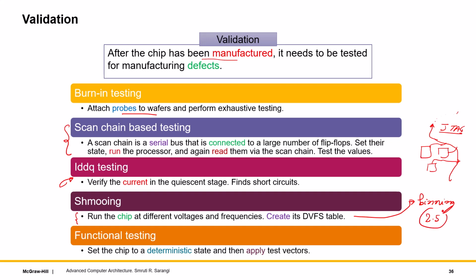So we'll sell a 2.5 gigahertz chip and of course charge less than a 3 gigahertz chip. Also, we can create a custom DVFS table, which means that at a given voltage, what is the maximum possible safe frequency at which there are no errors. So we can create a DVFS table that can look different for every single fabricated die because its physical properties are different.